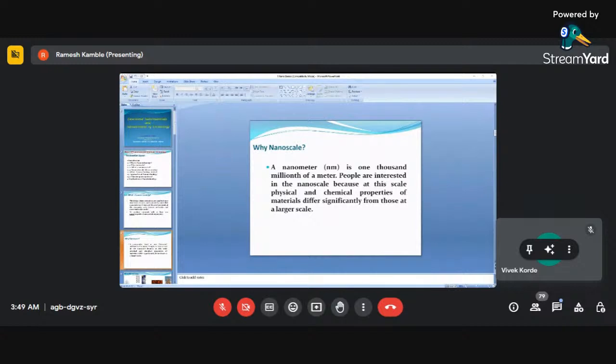Now, this slide is a little different than the routine one. Why? Because it highlights the ratio of surface to volume of a particular particle. So if you compare different particle sizes, we'll find that as particle size decreases, the surface to volume ratio is increasing. And this is very important for the materials, where we can get surprisingly enhanced, specific properties, so that we can tune particular physical properties for our application, and we can decide the material where it is more applicable and how we can tune either electrical, magnetic, or ferroelectric properties or many more. So in this way, the nanomaterial surface to volume ratio is very important.